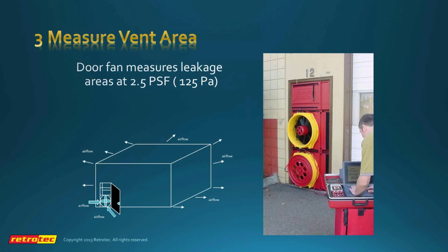The next one is that no matter how big your vent appears to be on paper, it may not be venting as much as you think it's going to vent. So there's 2 factors here. This one is, like we mentioned earlier, at what pressure does the vent open? Second is, how much free vent area does it actually have? And the manufacturer's numbers are usually kind of close.